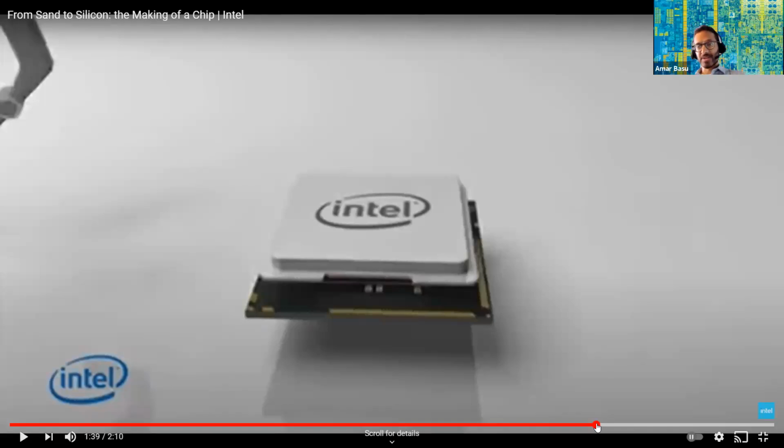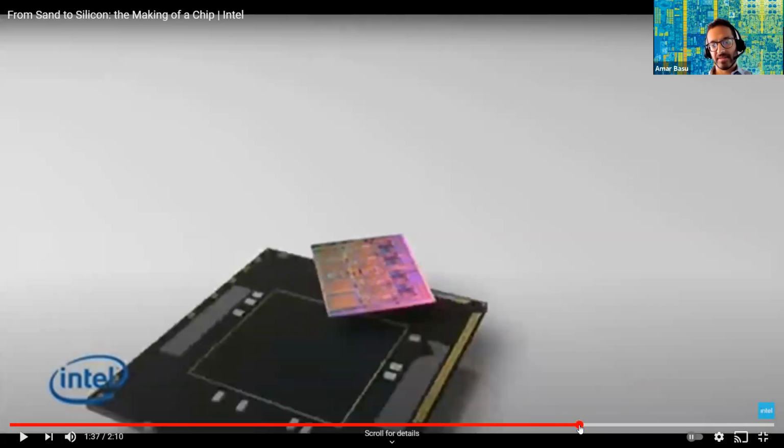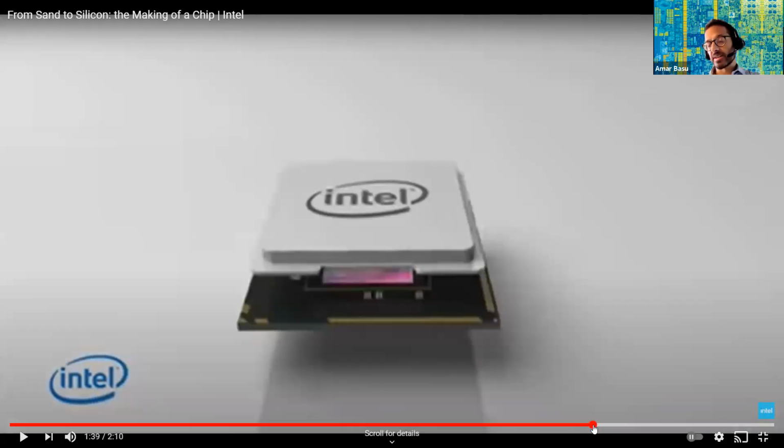Yes, that's one of the functions that it serves. These transistors are so tiny that if you start getting dust particles in there, they might malfunction. There's another important operation of this metal thing, and that is heat dissipation. 80 billion transistors switching on and off, it turns out it generates a lot of heat. And so we need a way of dissipating that heat. So this metal thing is often connected to a heat sink, and there's a fan in there that just keeps that chip cool.